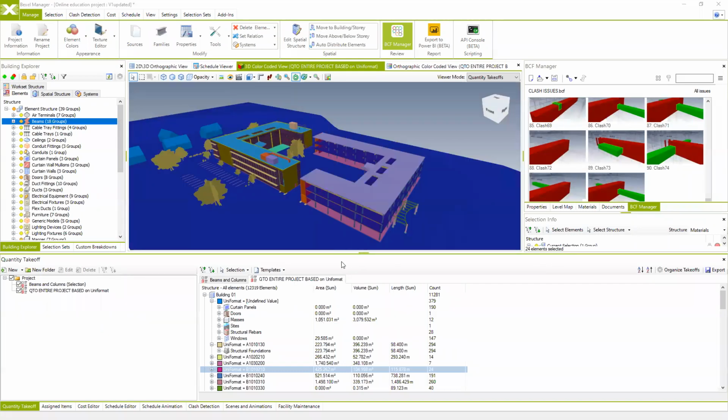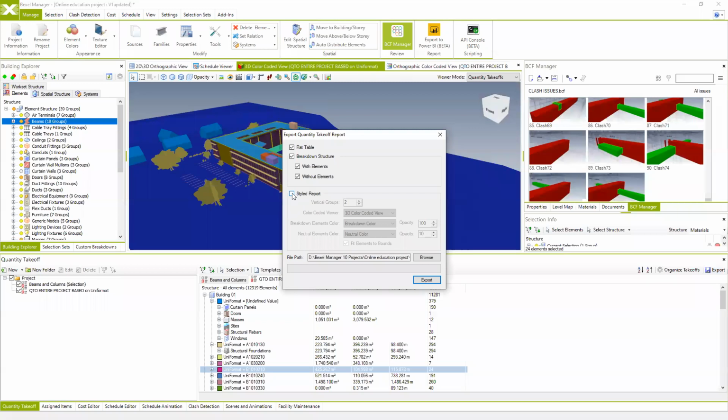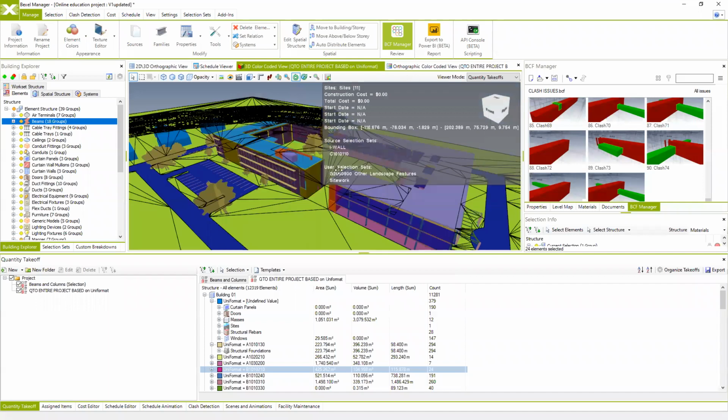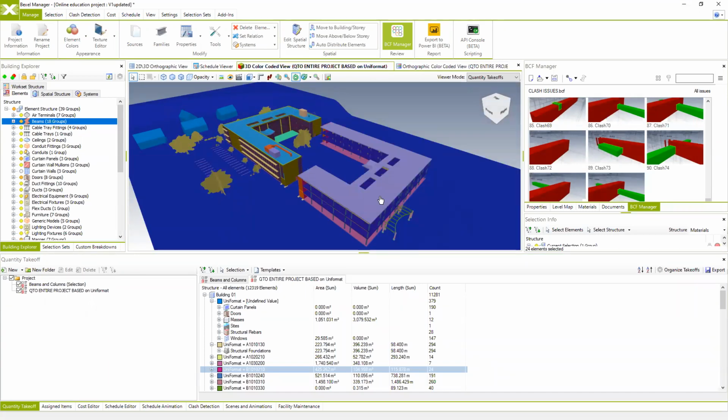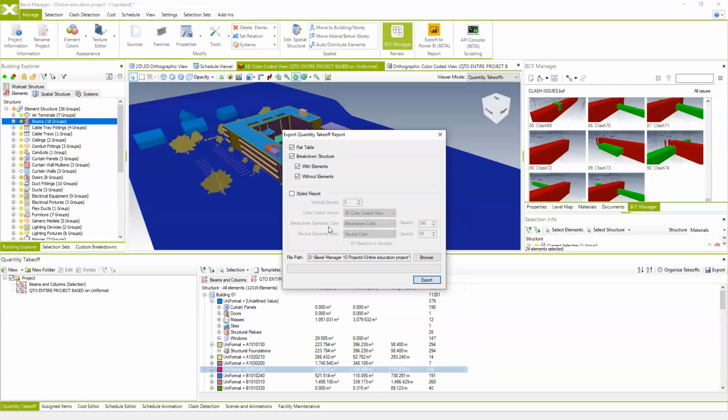But an additional way you can export your quantities is by selecting the style report, and then we can choose for the system to also include some visual representation of the included quantities. So in this case, I'm gonna unselect fit elements to bounds. So in this case, the screenshots will be created using this camera position for the next images that the system will automatically create.